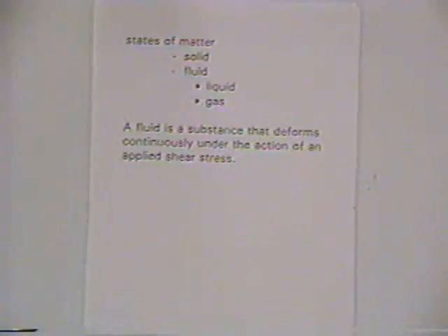With a solid, the attraction between the molecules is such that there's a rigidity, and I can rub my hand across this tabletop and the table will not deform. But with a fluid, the spacing of the molecules is such that the attractive forces will allow any type of shear stress at all to result in a continuous flow of the material.